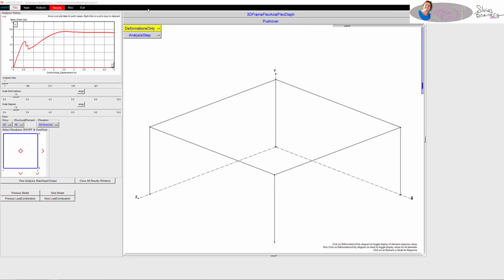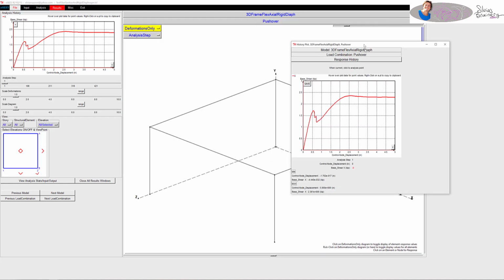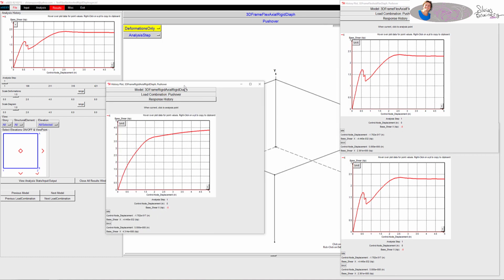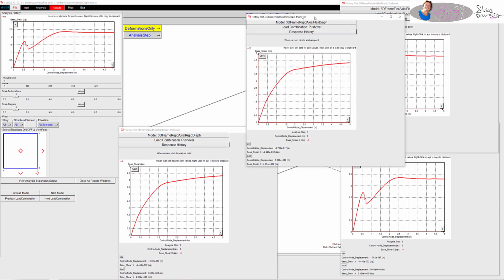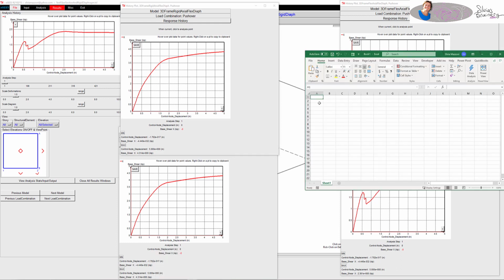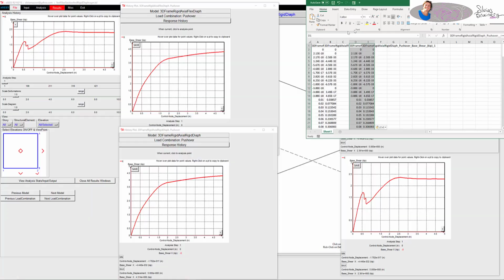Now, very, very important, this is a displacement control analysis where I have the same masses at all the same nodes. So I am not going to get any difference between a rigid diaphragm constraint and a flexible diaphragm constraint, because I am forcing the displacement to be the same because I'm applying the same forces. But as you can see, there is a significant difference between the model on the left, which is the one that has PM interaction in the beams, and the one on the right that doesn't have PM interaction in the beams.